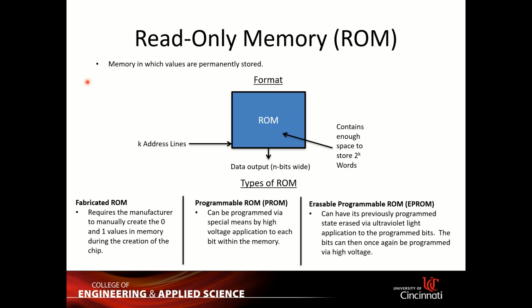So the way that manufacturers make this is they place the EPROM under some special UV light for a certain amount of time. Then that radiation will discharge the internal floating gates that serve as the program connection. So after everything is discharged, it's called erasing, all of the EPROM will go back to its initial state, and you can program it again.